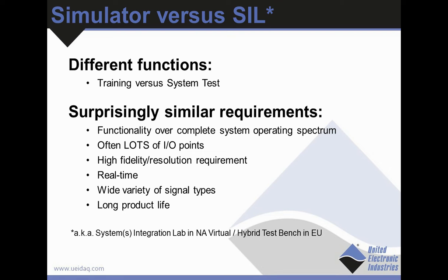If the RTD runs in your application from -100C to +300C, the SIL function or simulator needs to also run for the full distance. They're often quite big with lots of I/O points. They often require fairly high fidelity and resolution. Plus or minus 10 degrees C is not a real expected signal in either an actual system or a simulator.